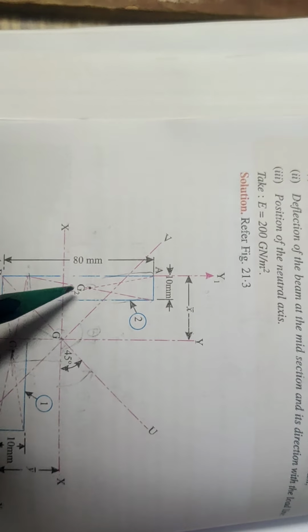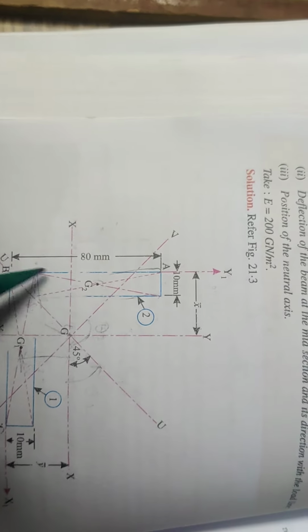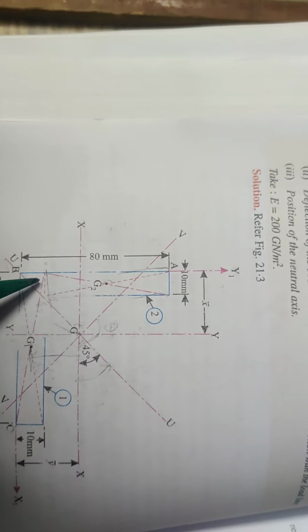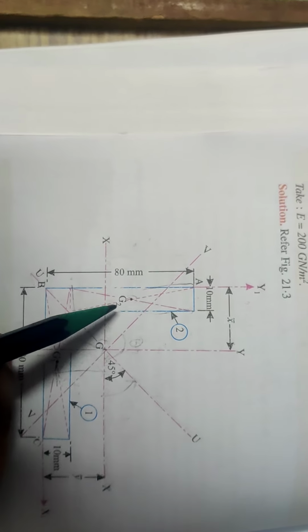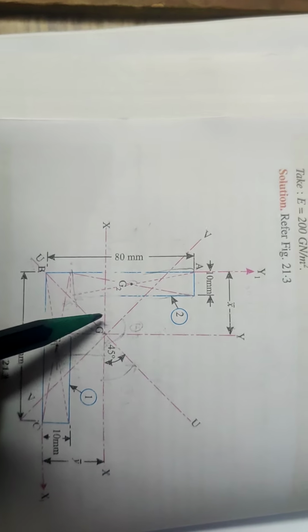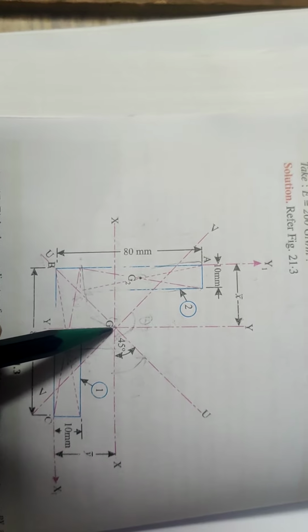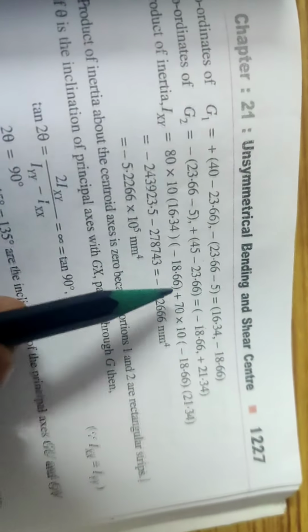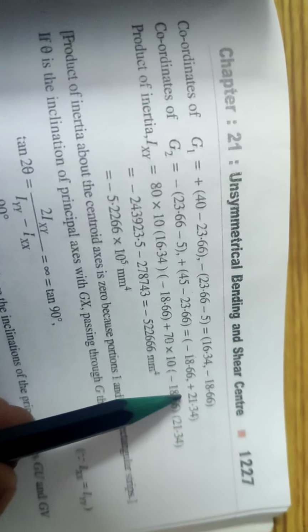Now I have to calculate the y value for G2. For G2, the centroid in the y direction is 10 plus 70 by 2, which is 35, so 10 plus 35 is 45. This 45 is ahead of the y value of G, which is 23.6, so 45 minus 23.6 gives a positive value. So the x value of G2 is minus 18.6 and the y value of G2 is